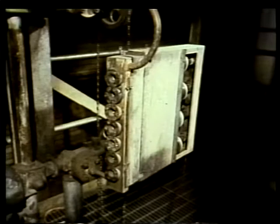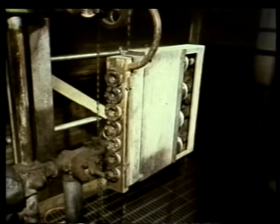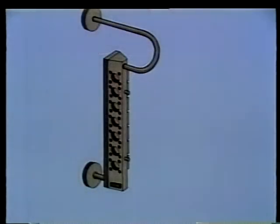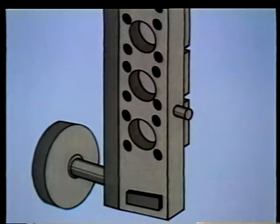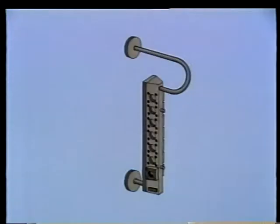The final common type of gauge is the multiple port gauge glass. Multiple port gauge glasses are often used on high pressure components. The multiple port gauge glass has a slight wedge-shaped metal body with a series of round openings on each side. The openings are covered with thick, round pieces of glass held in place with cover plates. Now, these cover plates are bolted to the body.